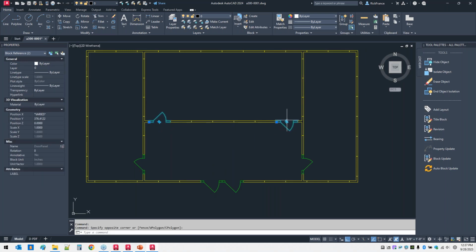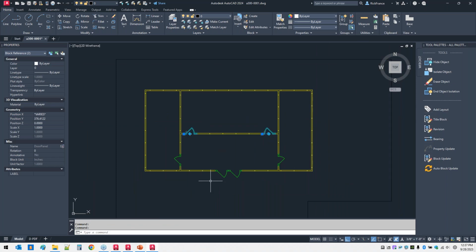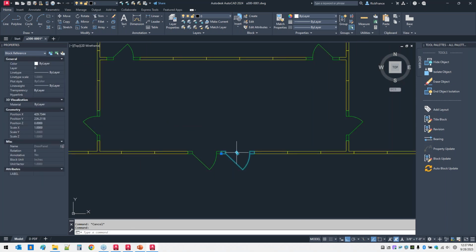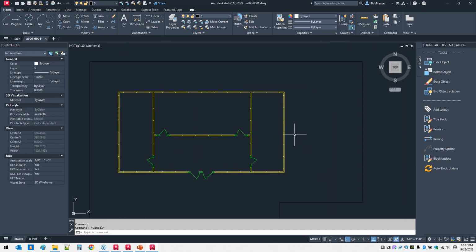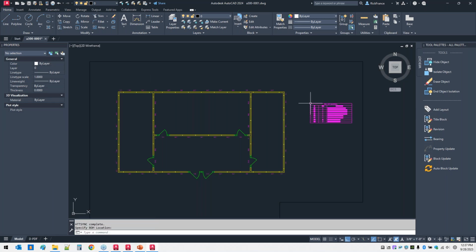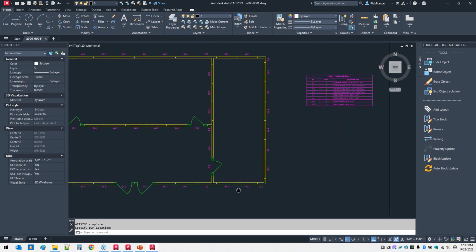Okay, so that kind of gives you an idea of what we can do. Again, I kept this one simple and only worried about those 3 commands, the parts of the command there, to where I was just doing doors and walls, and I didn't make them any fancier than what you see here. But this brings us to the last part of it. I got my layout drawn. Now I want to do, and this is vanilla AutoCAD, labeling those panels and creating a bill of material. One simple command, LP. They're all labeled instantly. Put there, and there's a little bill of material, a very simple one.